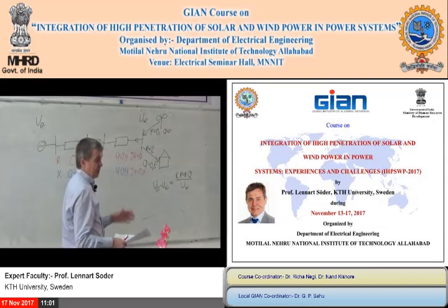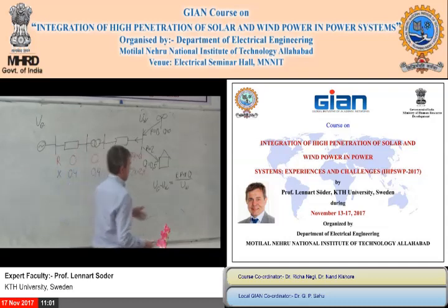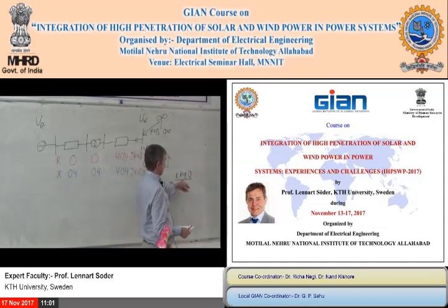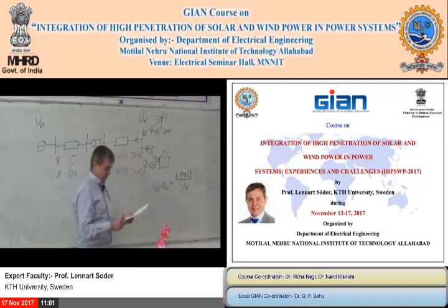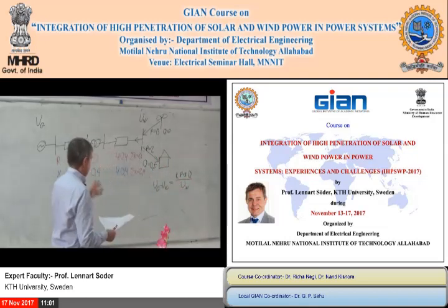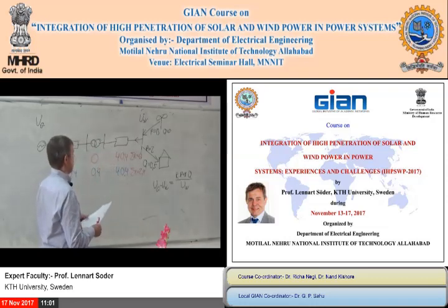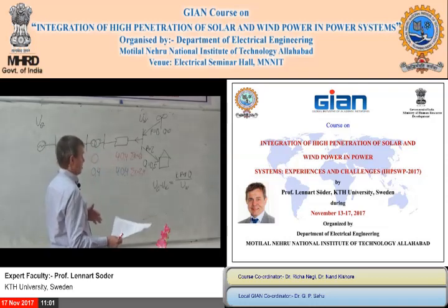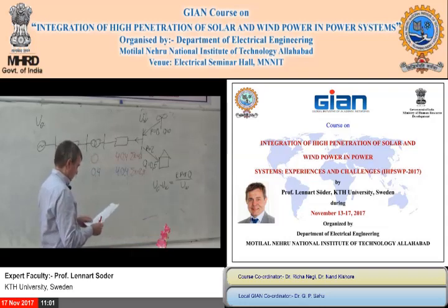But if you compare megawatt with megavar, then in this formula it's better to change the Q than the P. So it's in reality better to change the Q, and it has a bigger impact to change the Q by 1 megavar instead of changing the active power by 1 megawatt.